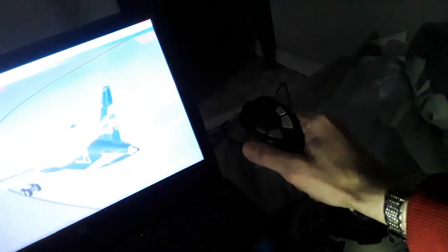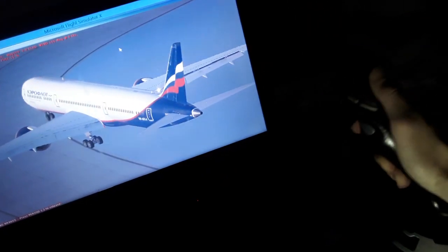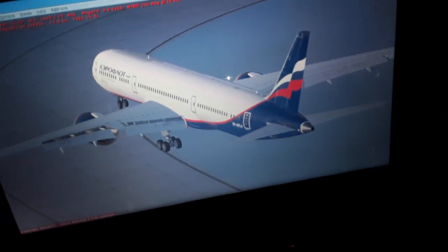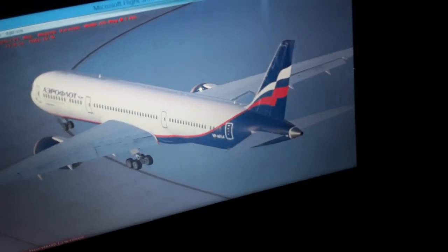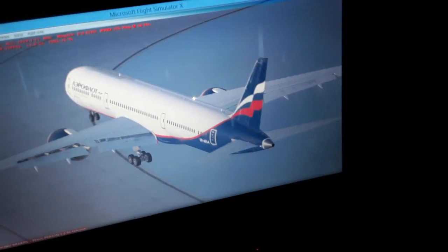You make left and right turns like this. It's the control wheel in the Boeing aircraft, so you make left and right turns using the side stick left and right deflection. You see the roll, you roll using the aerodynamic effect of the ailerons, spoilers and flaperons in the Boeing, or just the ailerons and spoilers in the Airbus aircraft.